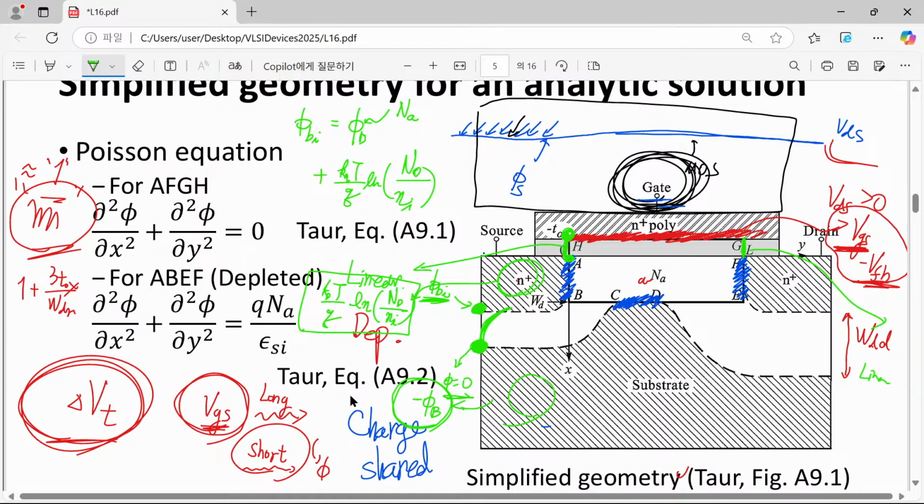Of course, you can ask me this question. Well, it means that the electric field is ever increasing when we approach this point. Yes, that's true. If we go to this metallurgical junction, then the magnitude of electric field is increasing, and we will have a maximum value here. After that, inside this N plus region, within a very short length scale, this high electric field can be neutralized.